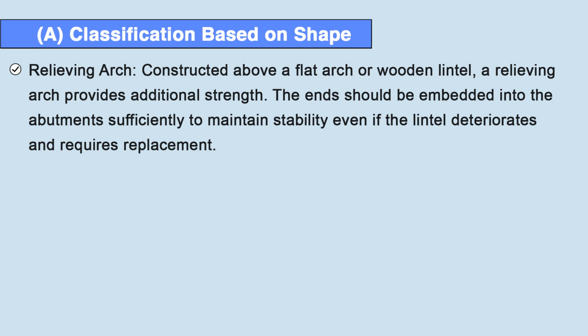A relieving arch provides additional strength, which means this kind of arch is constructed to increase the strength of an existing lintel. The ends should be embedded into the abutment sufficiently to maintain stability even if the lintel deteriorates and requires replacement.